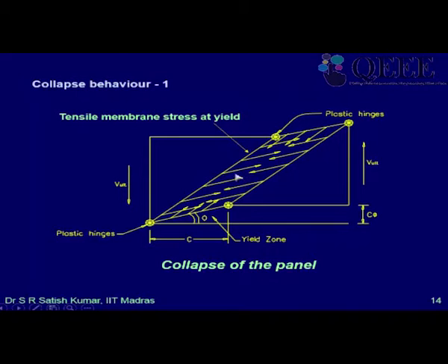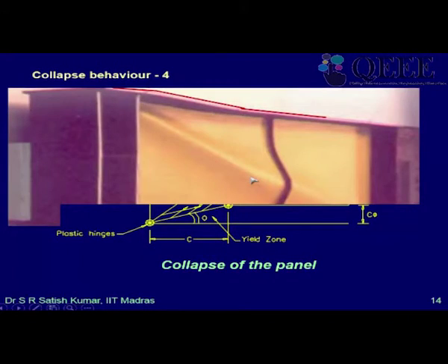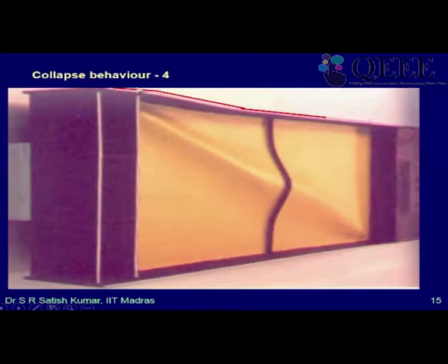Okay, and this width is called the tension field width. So basically that S is nothing but the tension field width. That also can be calculated. People have done enough research and given us simple formulas to calculate all this. Here you can see I have drawn a red line to indicate that somewhere here there is a kink, and the top flange comes down. There's another kink here, and then it goes this way, right?